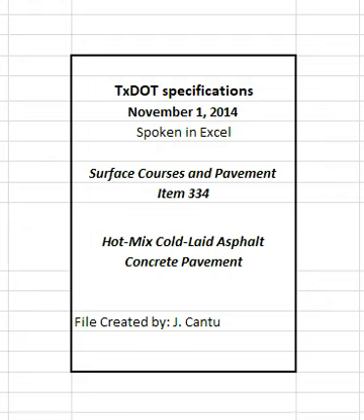For mixture produced by a weigh batch plant or a modified weigh batch plant, measurement will be determined on the batch scales unless surge storage or stockpiling is used. Keep records of the number of batches, batch design, and the weight of the composite asphalt concrete mixture. The composite asphalt concrete mixture is defined as the asphalt, primer, aggregate, additives, and any residual moisture that is not designated to be deducted. Where surge storage or stockpiling is used, measurement of the material taken from the surge storage bin or stockpile will be made on truck scales or suspended hopper scales.